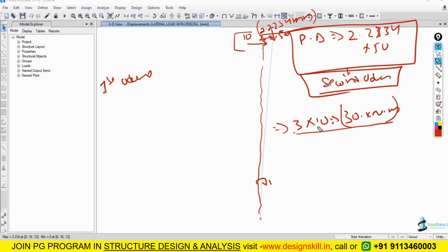Now the first order is due to the lateral load and the axial force that is there, the same thing, and due to that point it got deformed. Due to the lateral load it got only deformed, no? Then the effect that comes due to that, we will call it the second order effect, because it is caused by the first order, which was a lateral load here.